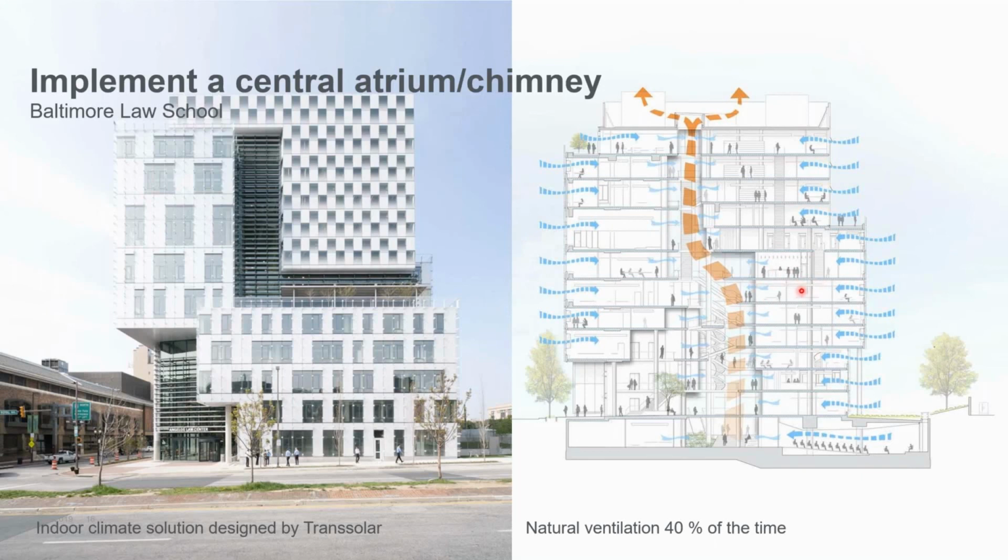But the short answer is that you have transfer vent solutions that can deal with acoustic issues, for example, in classrooms. It will have an effect on the flow rate because, of course, it's an added pressure loss in the system, but it is something that has been used in other designs before.